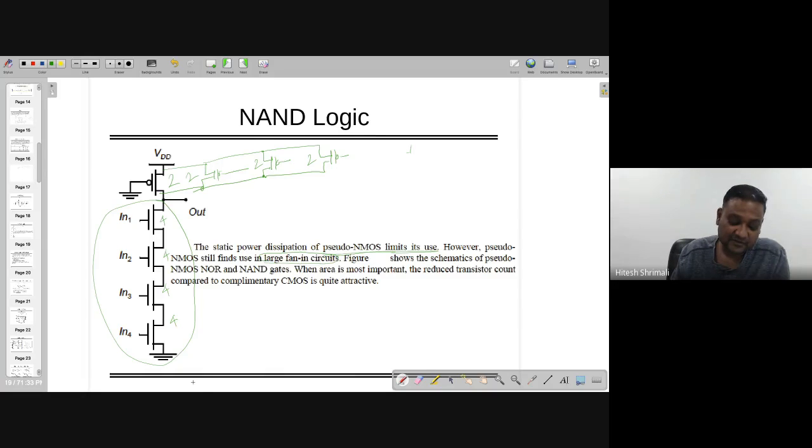And because of that, the input capacitance, if you look at this C in, it's actually 6, right? But in the case of this one, it might happen that this might be 0.5. I'm keeping 0.5 because effectively this is going to give me 1, and with respect to this, it's 0.5. So effective input capacitance is around 4.5 only, right?